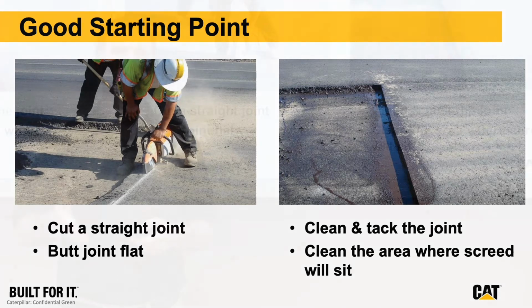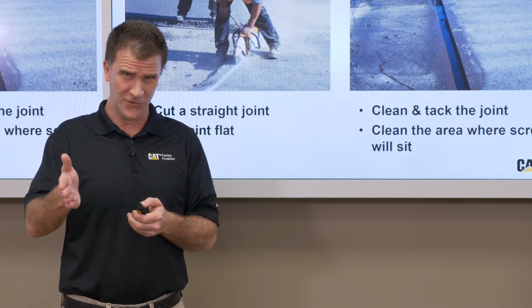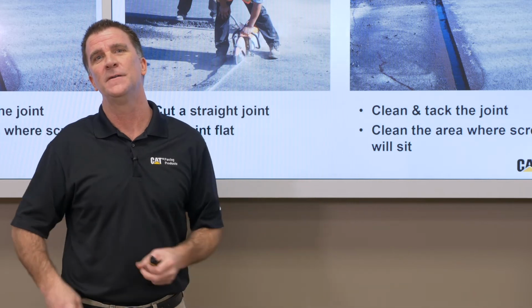There's other ways of doing this. Some crews at the end of the day, they'll put a board or a 2x4 or something square down there and then pave beyond it, pave a taper for traffic.